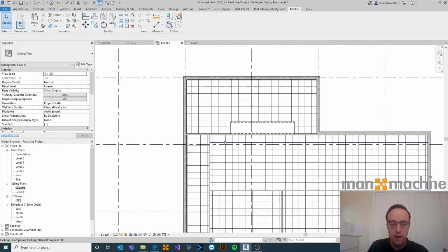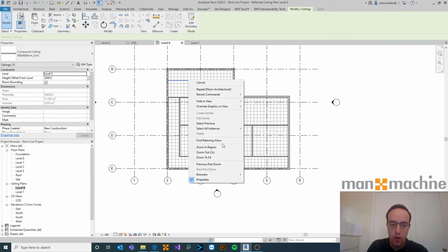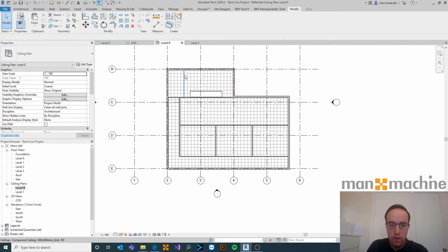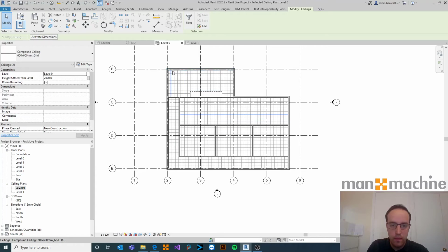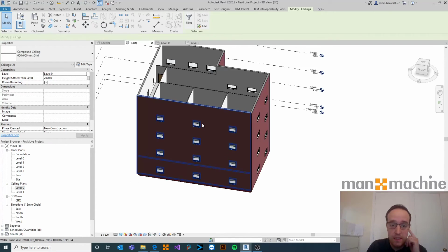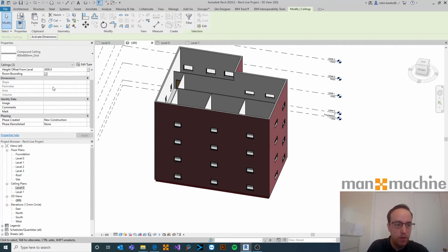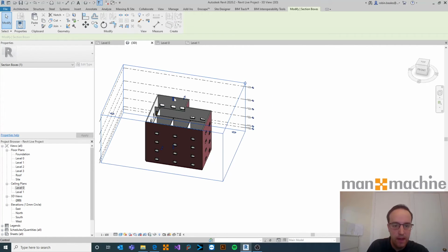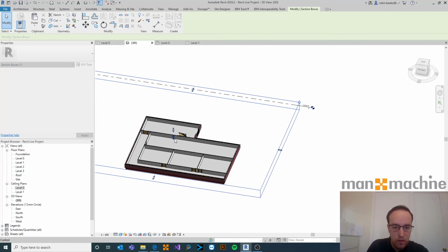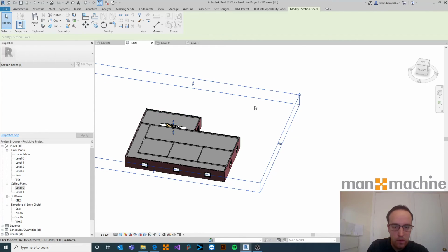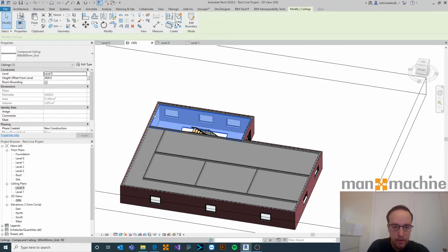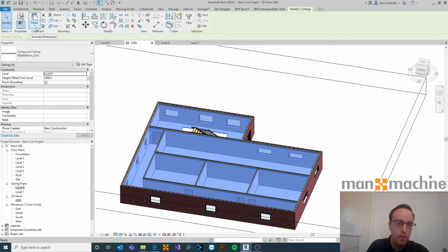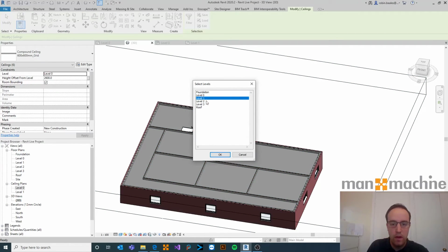And again, if you wanted to, just head over to level 0. Go ahead and select all instances of ceiling that you have in the view. So ceiling. Sometimes it's easier to just go and do that in a 3D view, putting on a section box, and just drag that section box down. Select ground floor. And then we can come in and say ceilings, right click, select all instances in the view, copy them and then paste them, aligning to 1, 2 and 3.